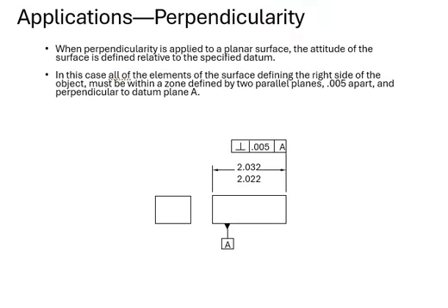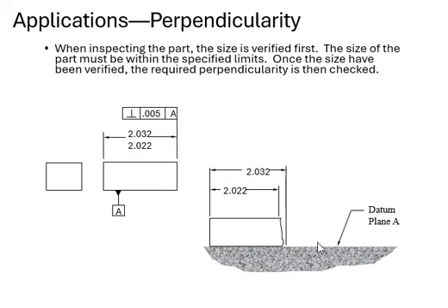Mostly we're doing the same thing, and everything that we do is in the feature control frame. Okay, so here we go, and this is our feature control frame right here. We'll control the perpendicularity by using this datum plane A. Our tolerance is given here, and this is just a size. All right. Now we're going to draw it a little bit bigger.